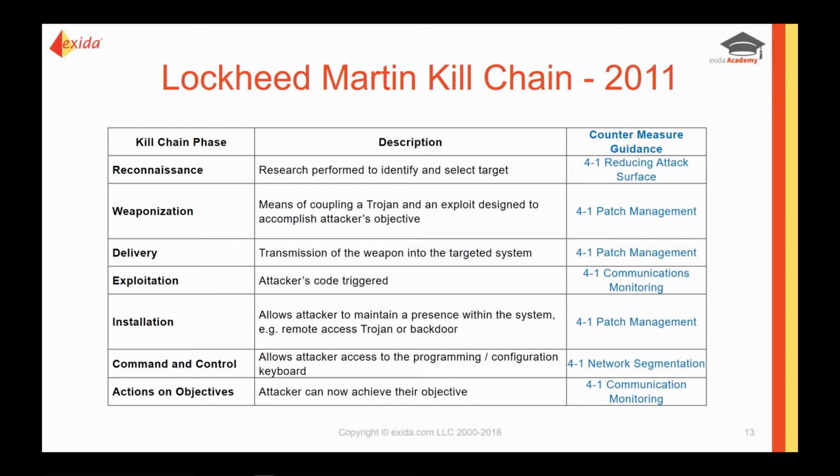So if we look at this kill chain, you can see that the 62443 standard does provide guidance in each one of these areas. This is a general model for hackers to follow. This model was to some extent followed in the Stuxnet attack that occurred. So for systems and environments that are aware of 62443 and the guidance that it provides, you can put up additional barriers and perhaps make the attack so difficult that they ultimately fail.